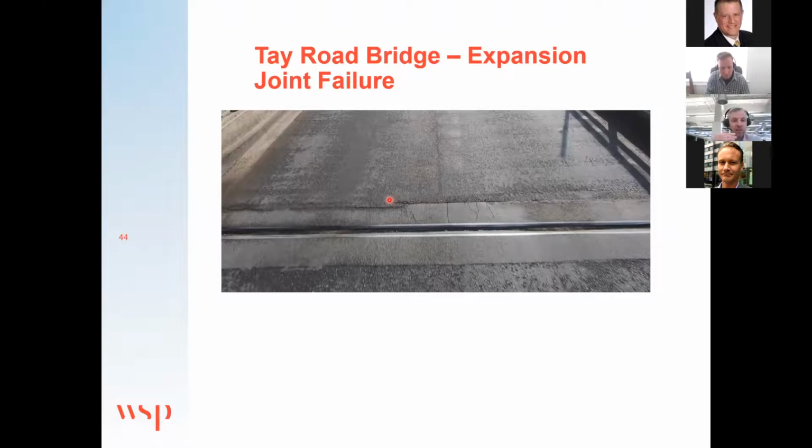But unbeknown to anybody, understandably, when you've got a survey system resolving to millimeter accuracy, very small amounts of inches, whatever is micro. The problem was, because of the wind and the exposure, this bridge deck was rising and falling by such an amount. We couldn't physically see it, so the survey team had to wait till the evenings, get the traffic off it, make sure it was quiet, to measure much more accurately in the survey. That's just getting the detail of every joint, every position.